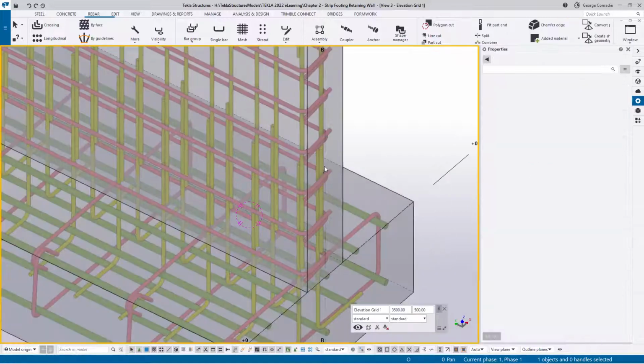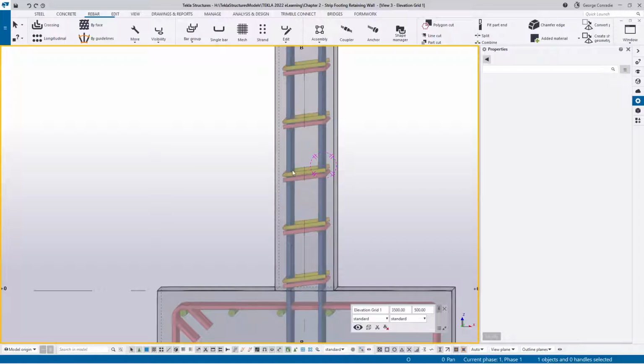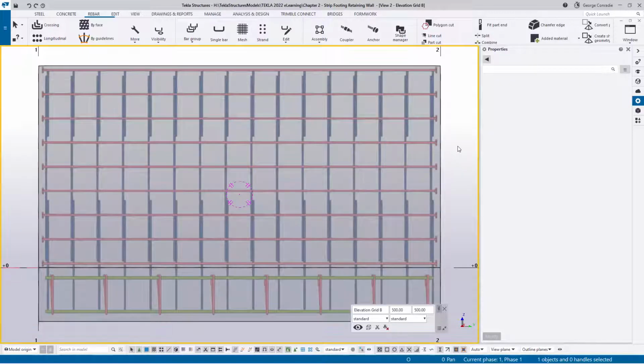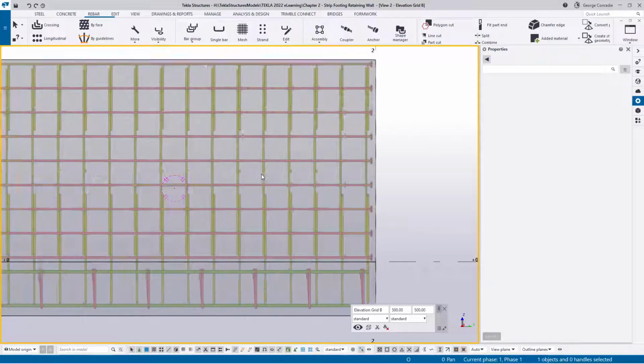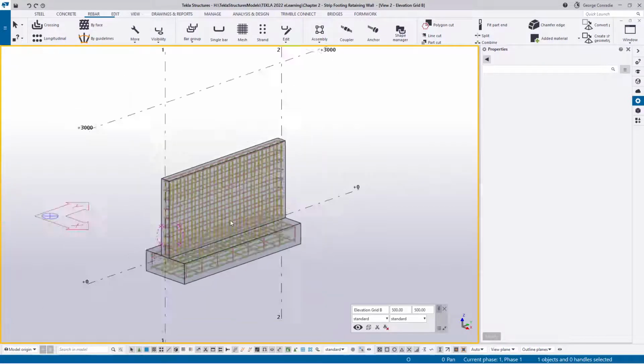Now, I wouldn't necessarily do this, because these hooks are quite short and it fits well within the wall. But it's very applicable if these hooks are longer and it actually pokes out or encroaches in concrete. You can rotate them up because that's what they normally do on site. The nice thing about this is it looks a bit funny when you're looking from the side, but if you look from the elevation, these bars are in line now, and just the hooks are sort of twisted, but it makes for nice drawing and dimensioning and so forth. And that pretty much wraps up this one.